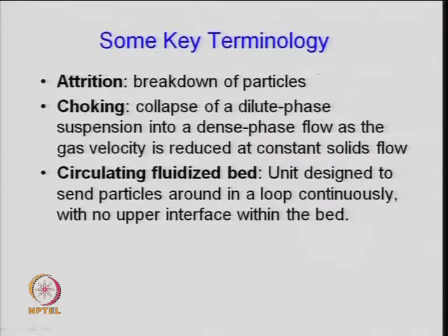That is again required when you have a cracking reaction and the catalyst activity decreases because of carbon deposition. So, you need a unit which is designed to send particles around in a loop continuously, with no upper interface within the bed. The solids are going up, taken to a unit where they are regenerated and then sent back into the system, and this is known as a circulating fluidized bed.